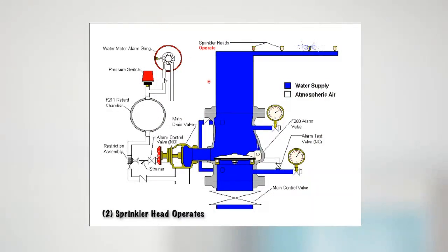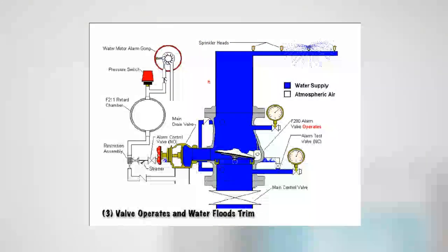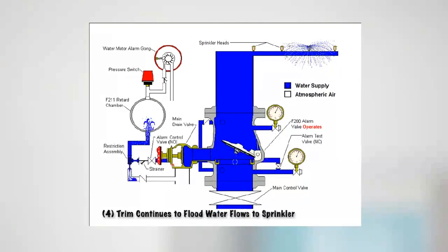Okay. We'll get a sprinkler head activation. Pressure above is reducing, so the pressure below is starting to raise the clapper, as you can see here. And at the same point, you'll have the annular groove filling up and the water starting to go down this pipe here. Okay, and it keeps going, and it starts to fill up the retard chamber. It's worth noting the retard chamber is there for false alarms, and it can minimise false alarms, especially in town's mains fed systems, where you get fluctuations in the main. Anyway, we've not got a false alarm here, it keeps going.